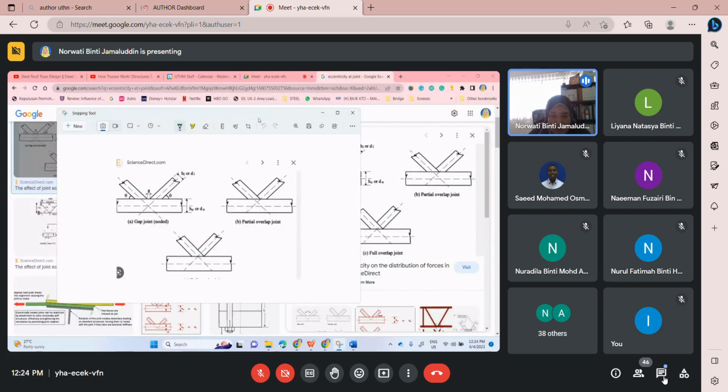Okay. Remember that you analyze using joint resolution or the other method. What will you have? You can get axial force. It could be tension. This one, compression. This is a member. Tension will be like this, coming out. So you can have it like this or like this.